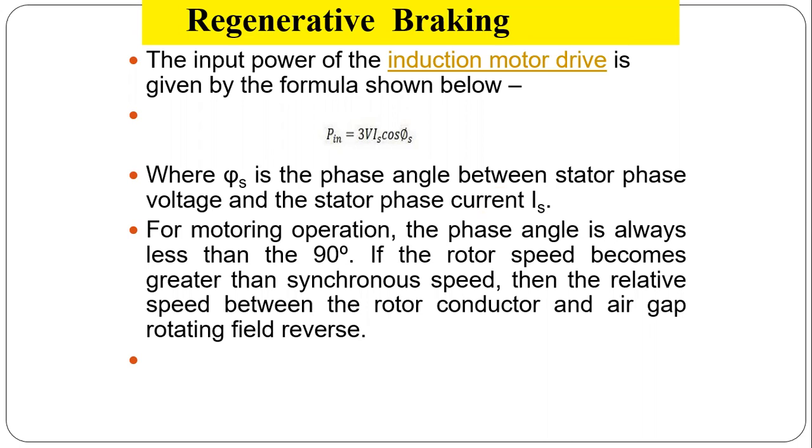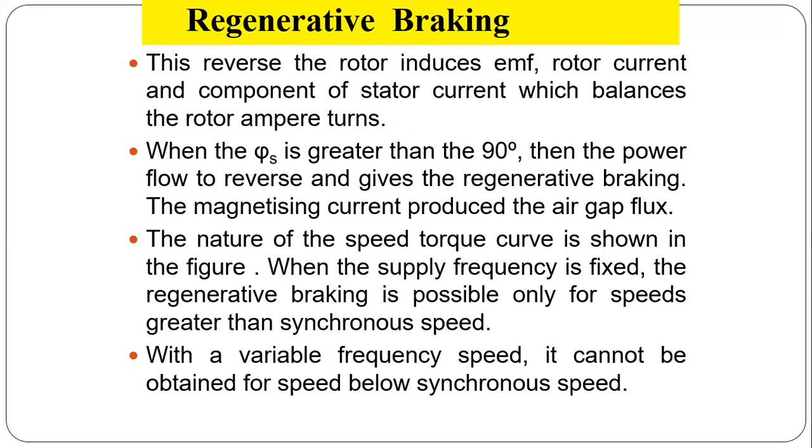The basic fundamental concept is that the rotor speed becomes greater than the synchronous speed, the relative speed reverses, and the machine works as a generator and develops negative torque. Let us understand in the next slide how it is developed.